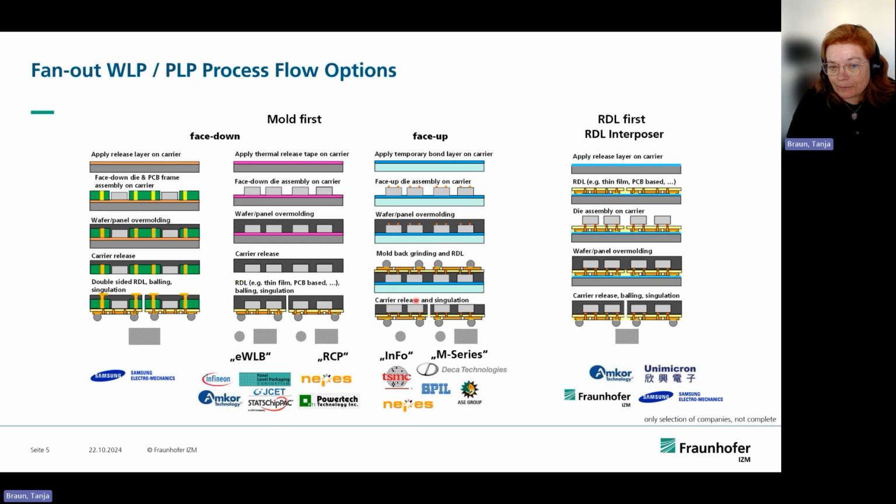And I think you need to be careful also with the chip thicknesses, and even if you now like to embed maybe also passive components or other modules, that is not so easy as if you do it for the face down version. The last option maybe we should look at this at the moment is RDL first.